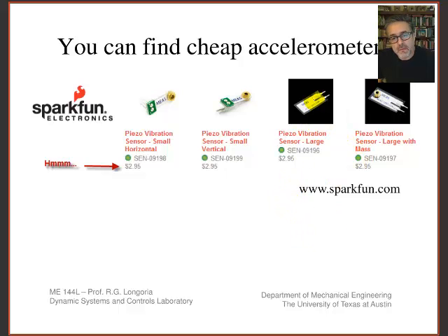Sometimes we do. We will use this little low-cost sensor, and then we'll wrap it with some signal conditioning. So nice, again, look at that, $3 for a nice little accelerometer. These are nice for integrating into different types of products where you need to detect motion. And maybe you're not concerned so much about the exact acceleration, you just want to sense relative motions. These are good devices for doing that.